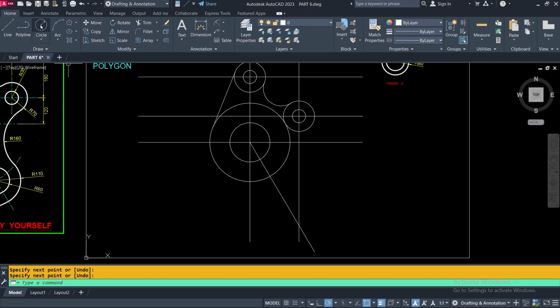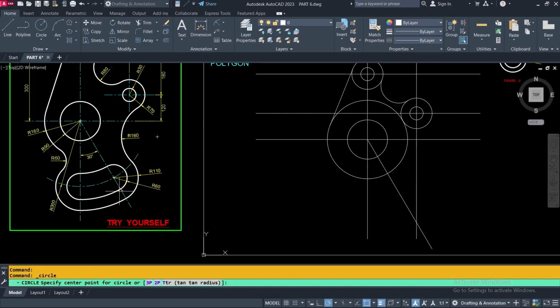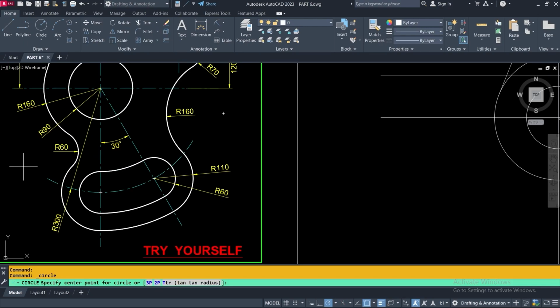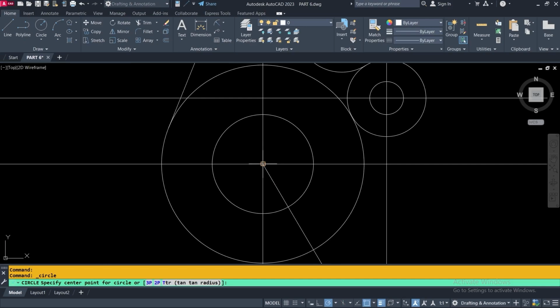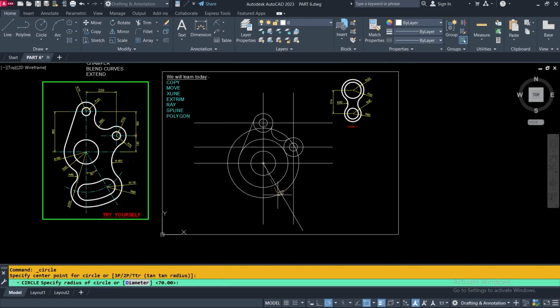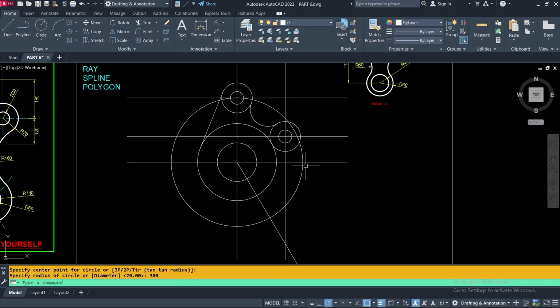I am going to draw a circle. Going to the circle tool, click on the circle tool. Here you see, now I am going to draw with the circle tool a circle of radius 300. Here it is written, this cyan color circle drawn with center line here. I am going to draw, the center will be here. The circles are concentric. Click, then typing the radius value 300, pressing enter. You see, the circle is drawn, but the full length of the circle is not required.